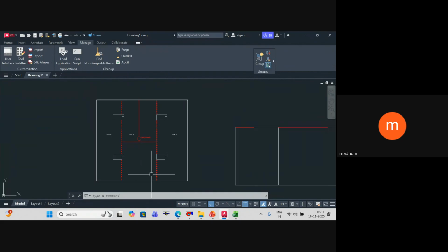If you have any format, can you share it with us? I mean, if you've done another calculation, share it so that we can work on that. For HVAC, I'll have it. For fire, I don't think I have it currently. I'll just check it. See, it's simple. For any pump, it's basically static head, velocity head, pressure head, friction head. That's it.